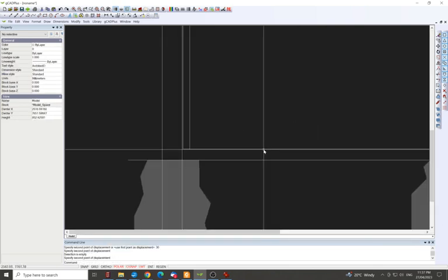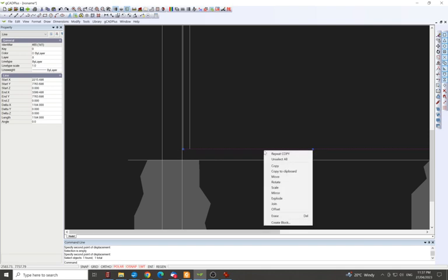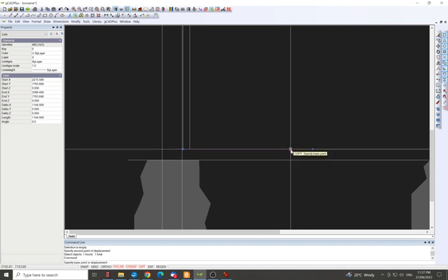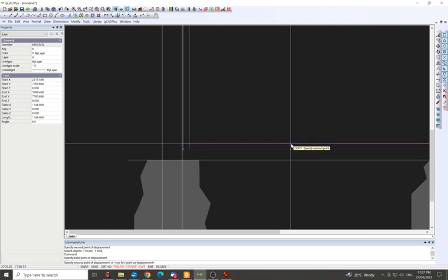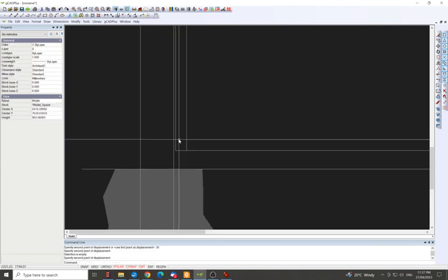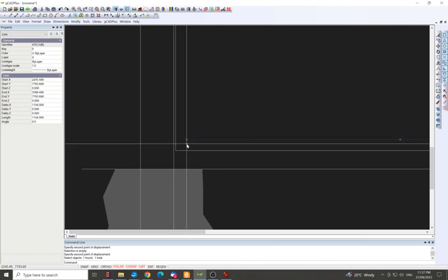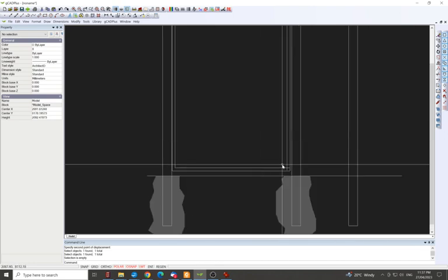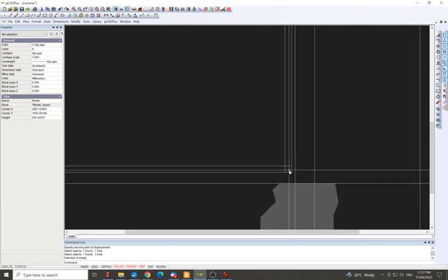So I'll just take you through. We select this line, right click, copy, select the line again, and then you move it to where you want it, because that's made the copy. Before you move it, see it's just moving freely. You get it in the position, so it polar tracks into its position to go straight up, and you just type your 30 and you're done. Now you can pull out these corners if you want, because typically these will be welded, but whether you keep them like that or that, I don't think it really matters for this drawing.